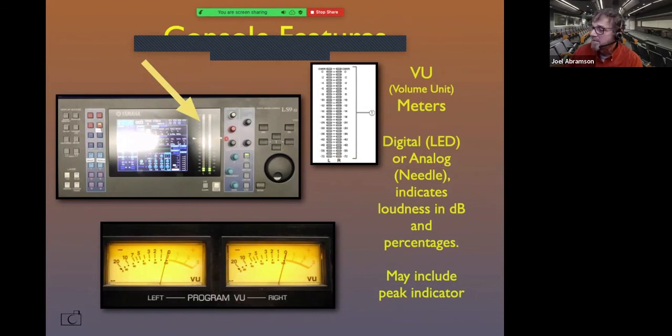We've set a unity gain right here, and this is where you want the VU meter to go, right? Just be aware that on some VU meters, on the LED meters, you can't go much over 0. When you go over 0, you start losing information. It starts over modulating really bad. So a lot of times -10 or -12 is where we set it, right? And that's our unity gain on these VU meters, okay?